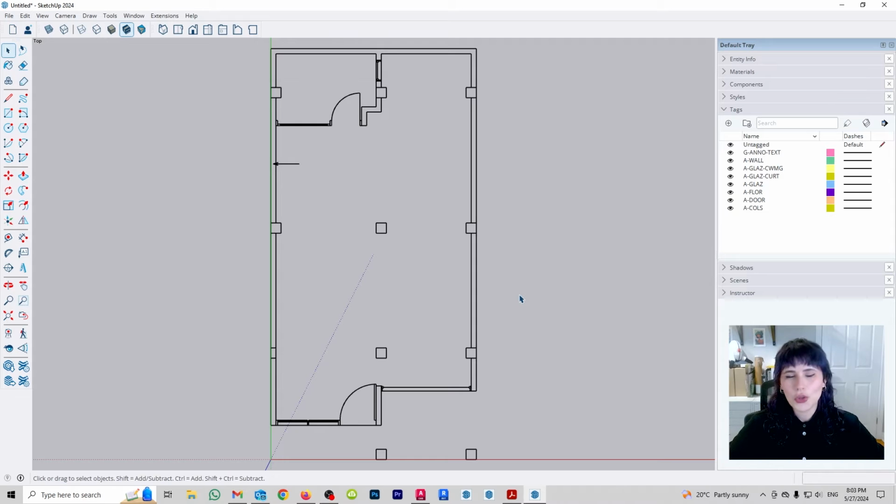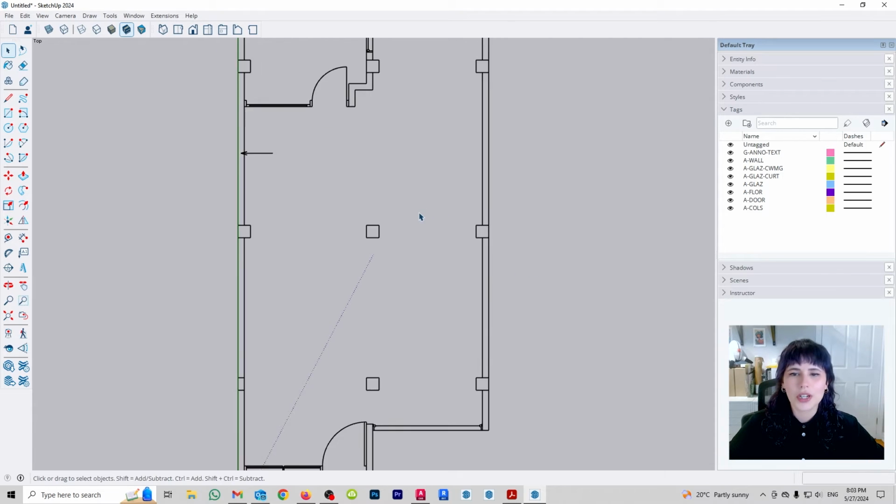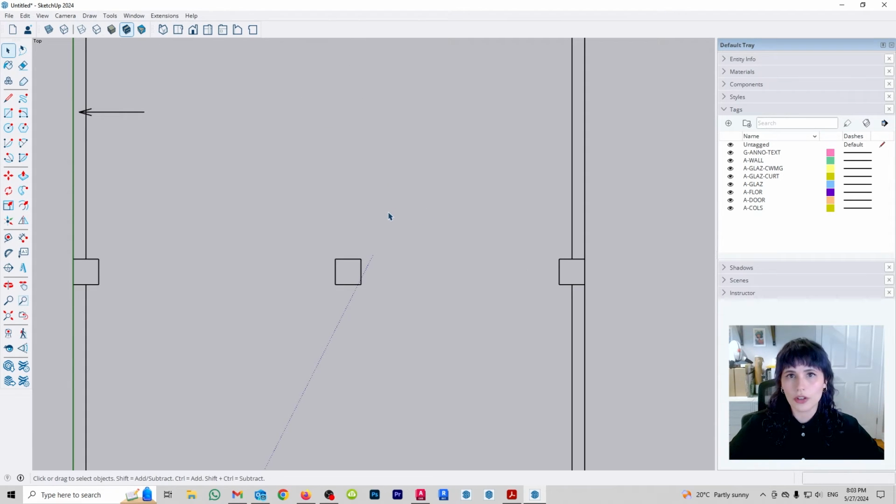So once again, you cannot just assume that the file is to scale. Don't do that. Don't trust the machines. They're not your friends. So we're going to use our measuring tape to verify the dimensions. Because we're converting from metric to imperial, you're not going to get the exact number. There's always some rounding that is being done, especially because I've set up that I don't want any fractions. I want to round to 0 inches. So in this case, it is helpful to know the conversion rates. So 300 millimeters is about 12 inches. It's about a foot. Not exactly, but close enough.